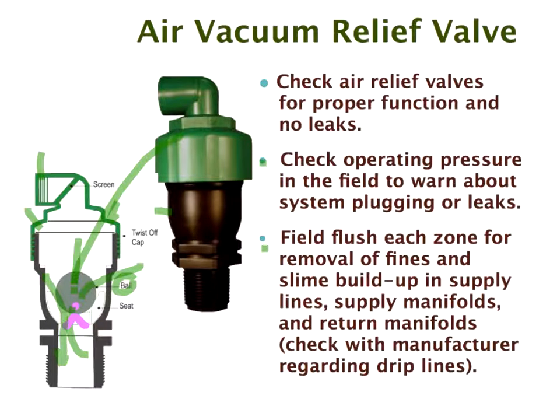Well, that isn't quite intelligent, is it? It sounded pretty intelligent to me. It's not. It needs a seat up here as well, because under pressure the ball will get pushed up, so it needs a seat at the top as well. Obviously the ball moves up here and has to seat.